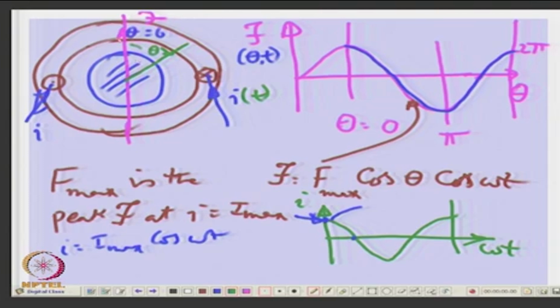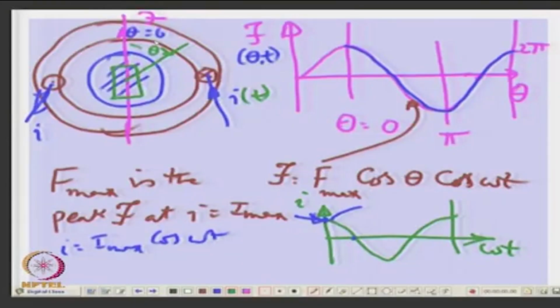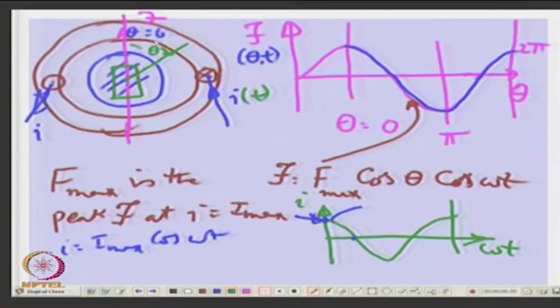So, we have always said it is like placing a magnet here, whose strength will go on changing with time, but the magnet will not change its position. Okay. This is the concept. If you look at the air gap, a single winding excited with AC, this is the picture that you have.